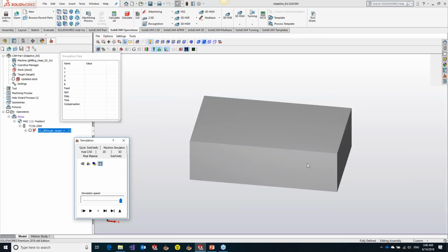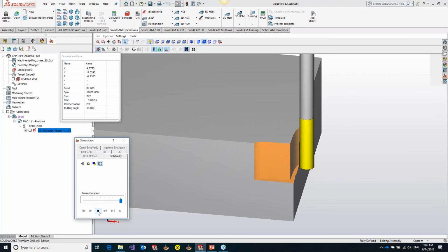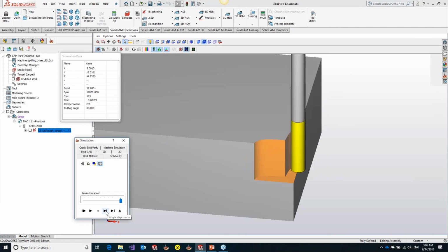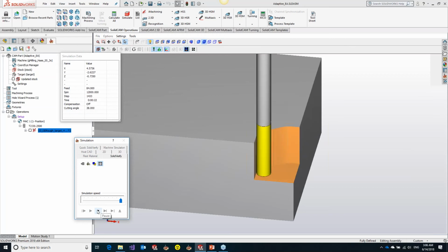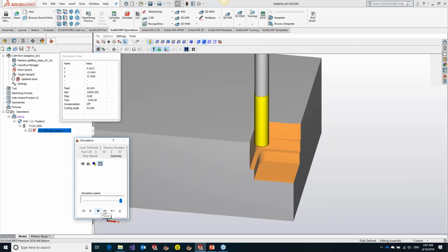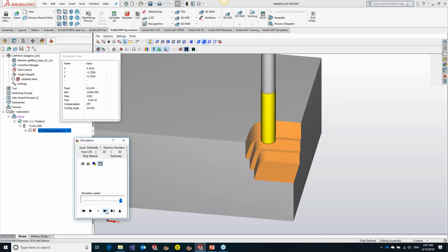And once again, I will try it. So the first depth of cut, we have our 36 to 38 degrees, and so 38 degrees, you're going to see 37, 37, 38, just rounding. So now you get a constant engagement angle through the entire toolpath.